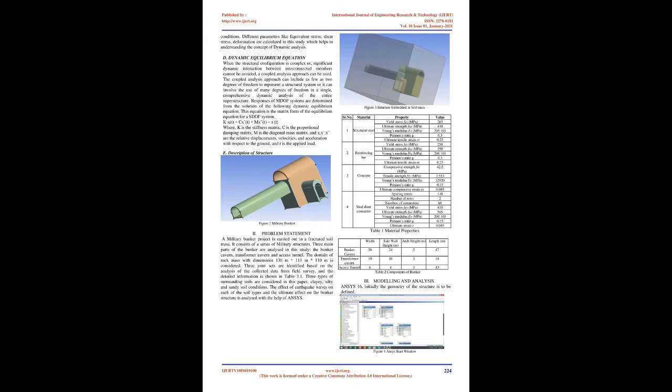Every structure has its own natural frequencies. When the excitation of a vibration on a machine coincides with a natural frequency of the system, the structure resonates with the excitation force, which leads to excessive, sometimes violent vibrations, which may lead to damage of the structure. Modal analysis is used to identify natural frequencies and their vibration modes.